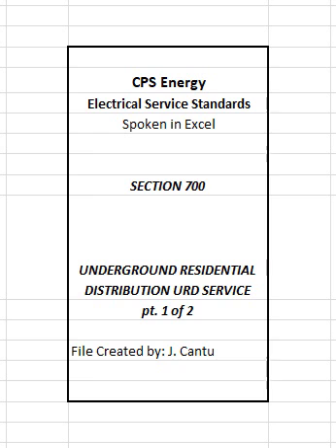A. Restricted use of easements. Customer shall not permit any structure, such as storage buildings, swimming pools, spas, decks, patios, carports, garages, concrete walks and drives, or equipment to be temporarily or permanently positioned over electric and/or gas lines or in their easements. Note: while easements are not required for routing of URD service laterals and conduits, CPS Energy will not permit temporary or permanent structures to be placed in a manner that will obstruct CPS Energy access for maintenance or repair to service laterals and conduits.